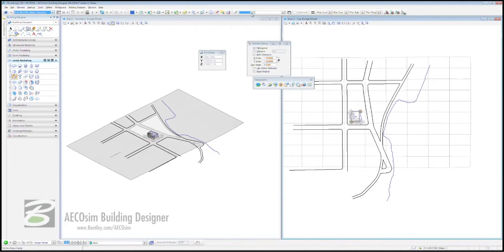Before we do that, we're going to select a part and family. We're going to select Site, and underneath that, we're going to select Earth. Now, the reason we do that is going to help us out in the long run, because it's imbuing our model with even more information. Now, our Solid by Extrusion dialog box is open. Make sure orthogonal is checked. You can check distance, because we're going to thicken this by 2 feet across the whole terrain, but there's another way of doing it.